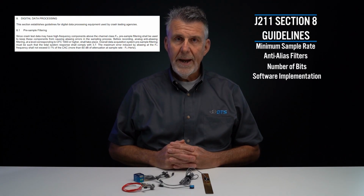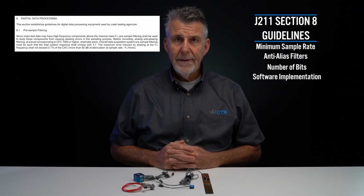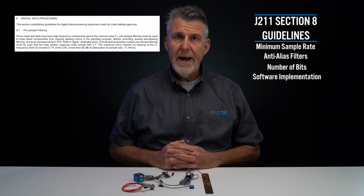Section 8 is entitled Digital Data Processing, and this is really where the rubber meets the road, so to speak. We have requirements for minimum sampling rate, filtering that's applied to avoid aliasing, the number of bits that the system must have, and even how you implement the software post-processing.